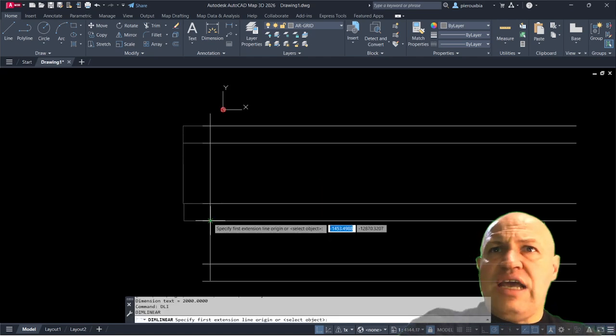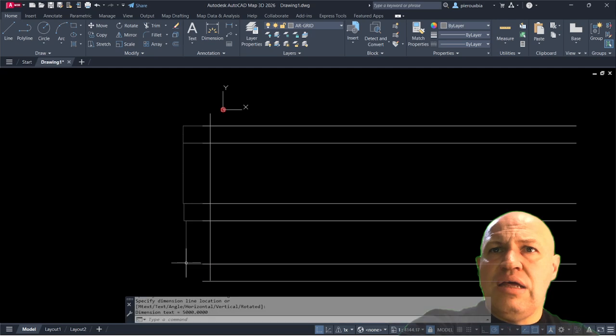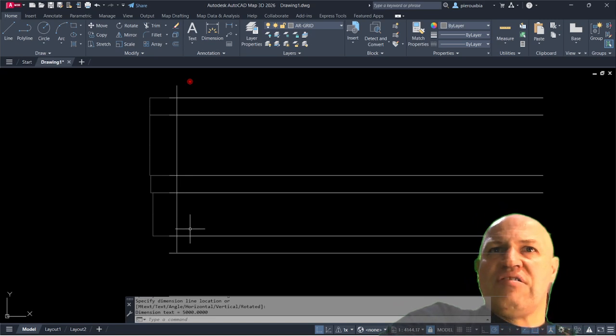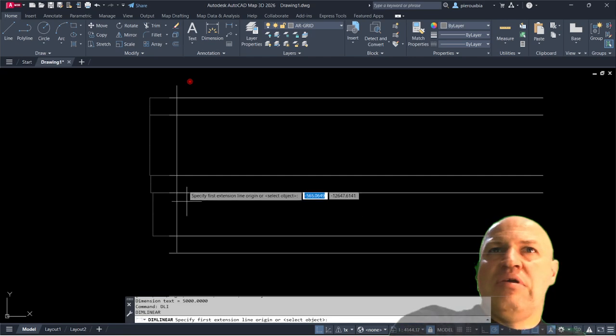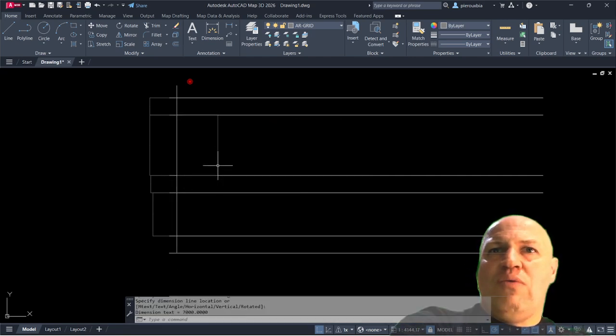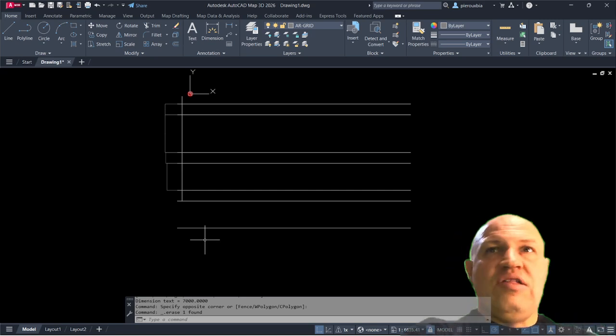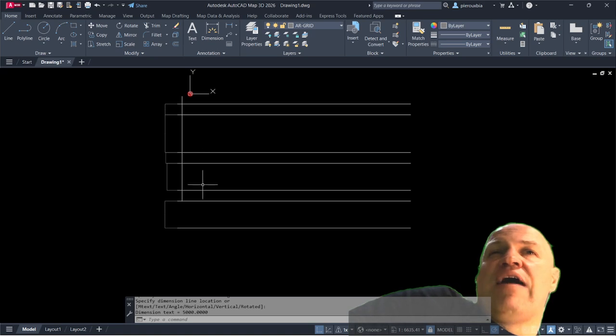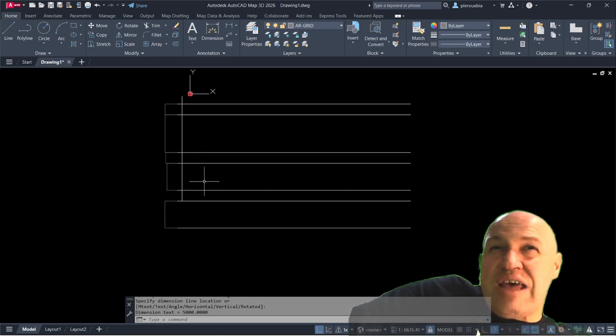And we're just going to check this last one here. Right. So what is actually happening here is that this one is 5 meters and not 7 meters. So can we think about what we think is going on here? What I think is happening is that, and you'll see that the first one is the right distance. This is 7 meters, but this one's only 5 meters. I think this is dimensioning from the wrong line. I think instead of saying 7 meters from this line, it's saying it's 7 meters from that line.